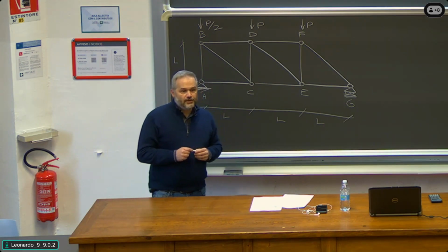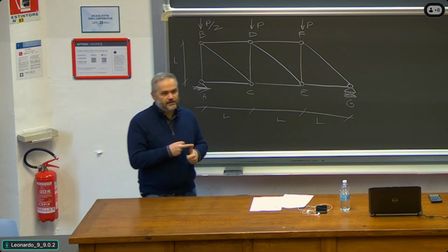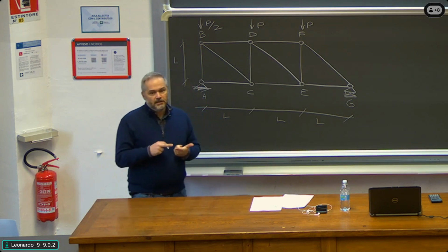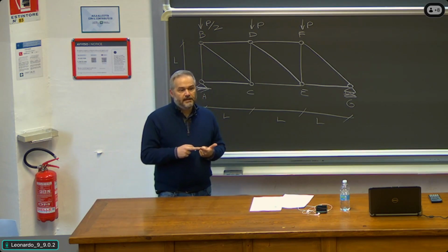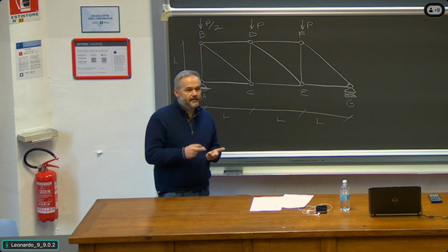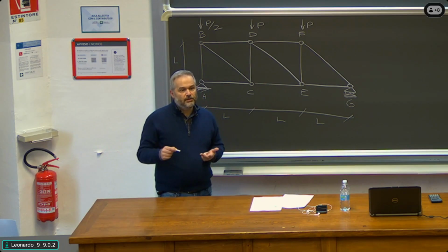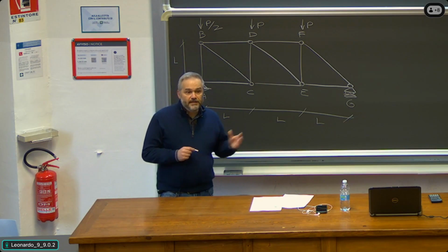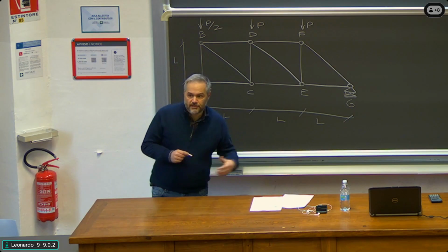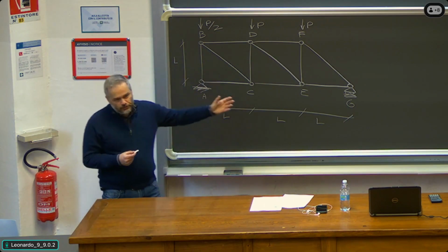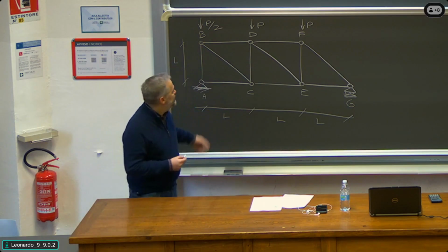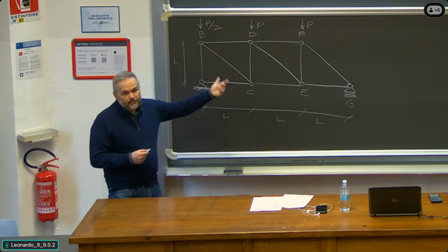These golden rules are: the member is straight, the boundary restraints are hinges, and there are no loads applied on the member. The only loads applied are at the ends of the members. When we study this type of structure with these hand calculations, we are neglecting the self-weight, which of course in reality is there, and it's a distributed load along the member.